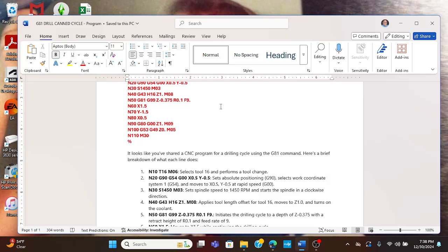The coolant also washes away the metal chips so that the metal chips do not scar the workpiece. So sometimes, with certain workpieces, the metal chips will scratch the workpiece. So again, you're trying to keep the tool cool, which extends the life of the tool, and you're washing away the chips, which actually gives the part a better surface finish.